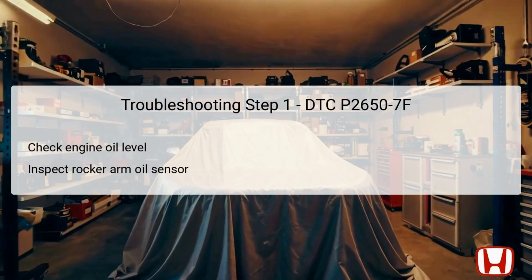The second part of this step is inspecting the rocker arm oil pressure sensor itself. This involves checking for any visible damage or disconnection in the sensor wiring and connectors, as such issues can lead to faulty readings. If the sensor is intact, applying a diagnostic tool to read live data may provide insights into its operational status during engine operation. If the oil level is adequate and the sensor appears operational, further investigation into the VTEC system and its components is warranted to determine subsequent points of failure.